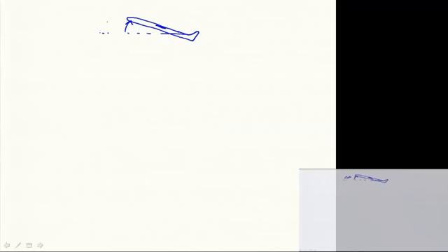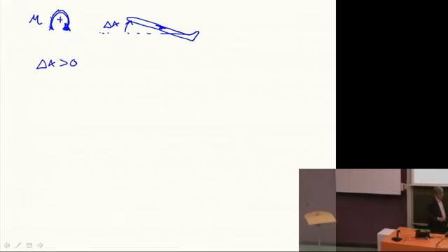If the alpha increases, if delta alpha is positive, then remember that the y-axis is pointed away from us in this picture, and the standard convention for moments, for plus moments, is in this direction in this picture. So nose up. Nose up is positive. So what do we want as a reaction to a positive change of the angle of attack? What kind of moment do we want? Positive or negative? Negative. Yes, has to counter the direction.